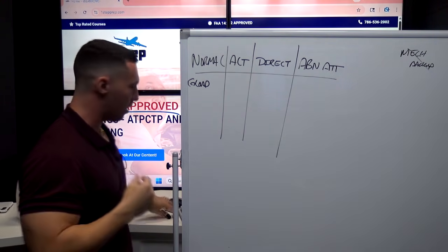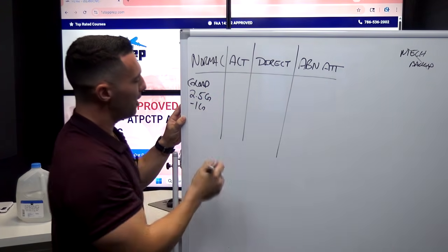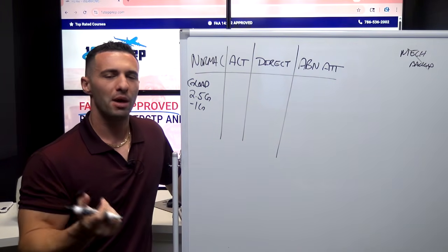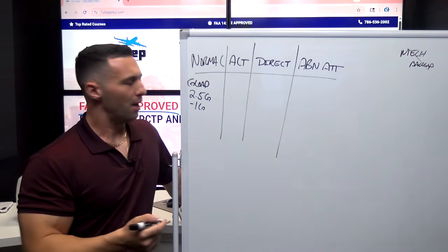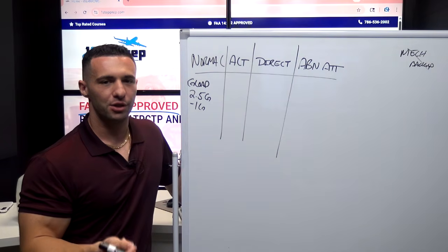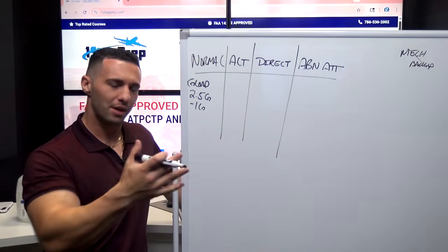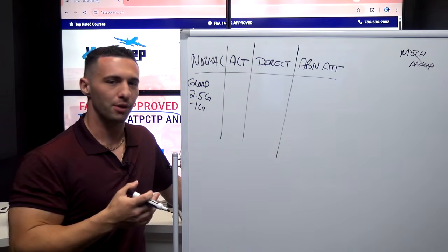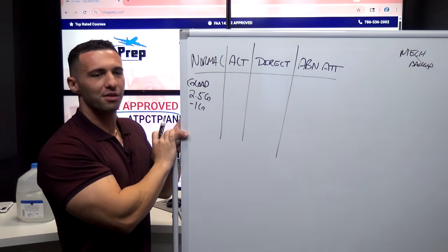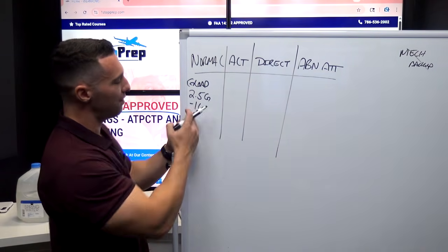So with the normal law, G load protection, when we have 2.5 Gs to a minus 1 G, I just want to pause at the 2.5 G for a second and talk about why is it 2.5 G? Who came up with 2.5 Gs here? And you should know that ultimate load, which is effectively the G load where potentially things could break off the airplane, is 3.75 Gs. So they're giving us a considerable amount of margin or buffer before we ever reach anything like that. So that's your G load protection. That's assuming we're clean. And then of course, if we're dirty, it would be 2 to a 0 G. So that's your G load.